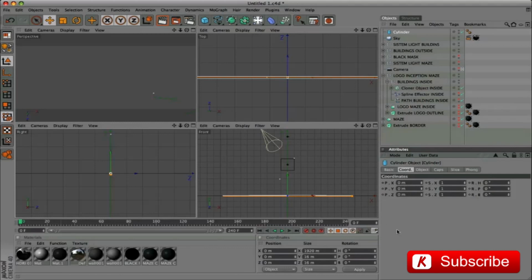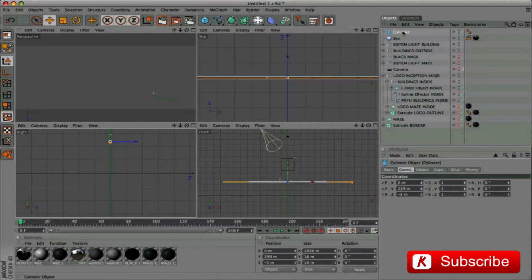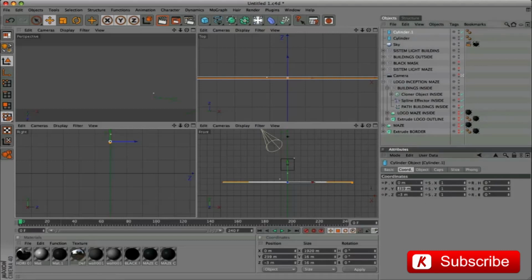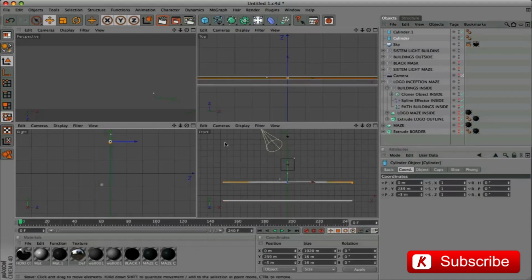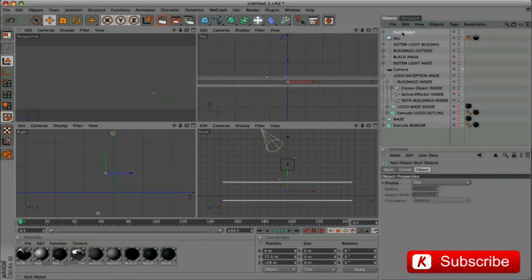The position coordinates are y 300, and z -3 meters. Duplicate the cylinder, and modify y -84, and z -55 meters. We modify the radius to 6 meters. We group the 2 cylinders, and rename building light reflection.